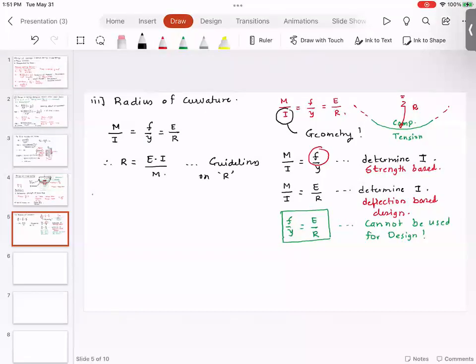And the last step is we had to find out the deflection at the center. And that is delta is equal to L square divided by 8R. So this actually defines the entire leaf spring design. Any questions on the leaf spring design?